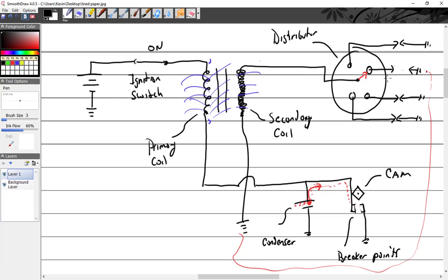So your coming in speed is defined as what? RPM. You get complete spark, the lowest speed at which you'll get spark throughout. Okay, so the coming in speed of a magneto is the lowest speed at which it will consistently fire all gaps. Now, you can't just say something like that, especially in aviation, because if I made the gaps 1 millimeter, I bet you could run that thing at about 10, 15 RPM and it would work just fine. If I made them 6 inches, they ain't never going to work, right? So you have to have a calibrated point on there.